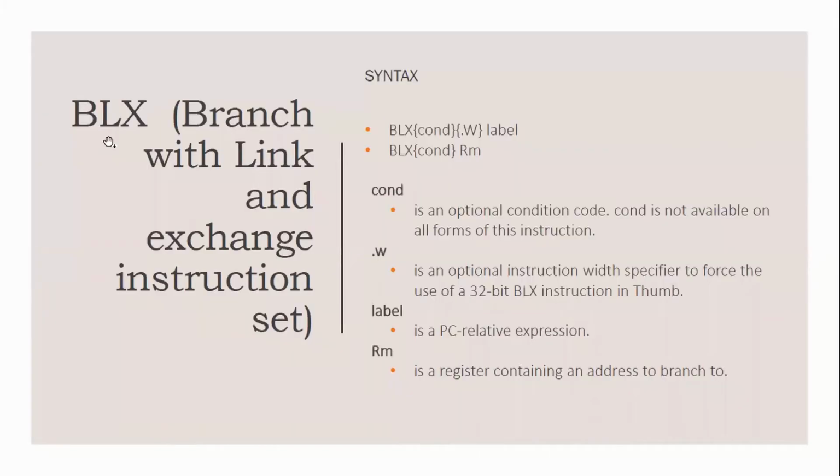Thank you. BLX is a branch with link and exchange instruction set. Syntax. Example, BLX{condition} label. Next, BLX{condition} Rm. Condition is an optional condition code.